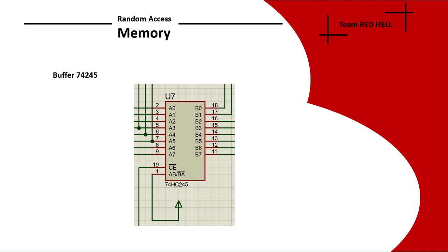We can say that chip enable or CE is active low, which is denoted in our simulation as RO or RAM output. When enabled, the buffer acts like a positively biased output and passes the data. Otherwise it does not pass the data. This property is used in order to prevent the data from coming to RAM from the bus. RO is controlled by a control sequencer, which will be discussed in a later video.